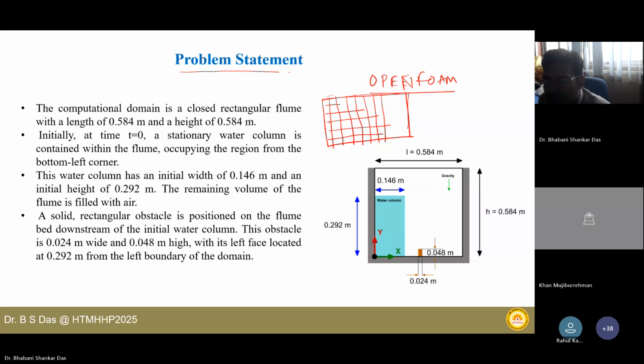So if we disintegrate the domain into several cells, several nodes and elements, you can see the several. I have discretized the domain into multiple rectangular and square type of grid. And now if you want to solve the differential equations in this grid, we will get the value in these locations, in these nodes. For different space and different time, what is the value of depth of flow, discharge of flow, we can get in these nodes only.